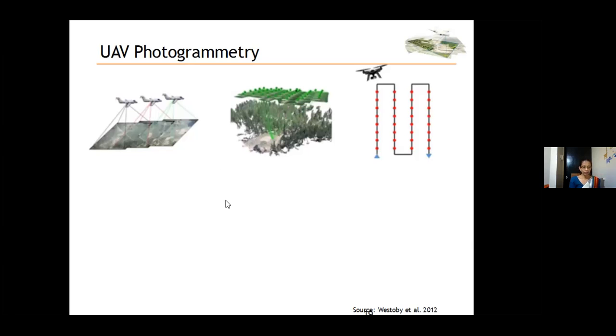If you go to traditional photogrammetry with a high quality camera, we know everything about the camera, such as camera model, focal length, principal point, orientation, etc. We can control flying height and capture photographs by looking directly down, that is, vertical photographs.